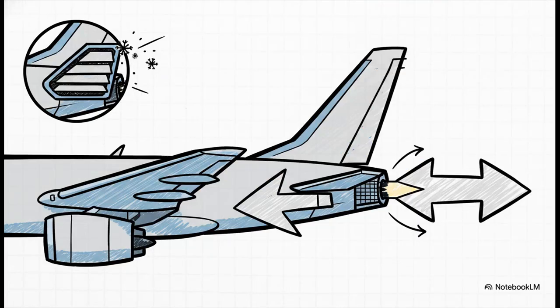Now, let's map out the physical airflow. Intake air is drawn through a screened inlet duct right on the right rear of the fuselage. Then, after the turbine does its thing, those exhaust gases flow through an exhaust ejector and are discharged upward at the very aft end of that titanium tail cone.